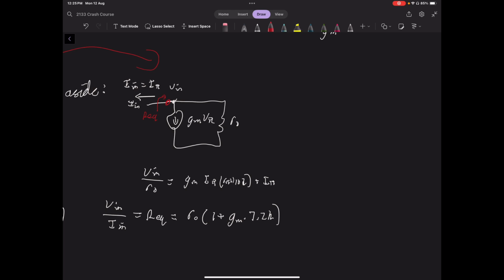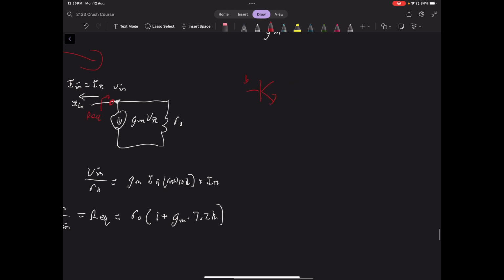And while we're here, I'm actually going to highlight a common trick that happens with BJT amplifiers. So obviously, this is our BJT with our base, collector, and emitter. And then the small signal equivalent circuit looks like this. That's our gm v pi, and over here is r0, and that's r pi and plus minus v pi.